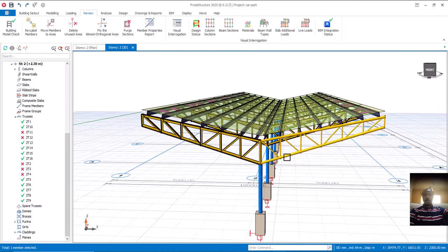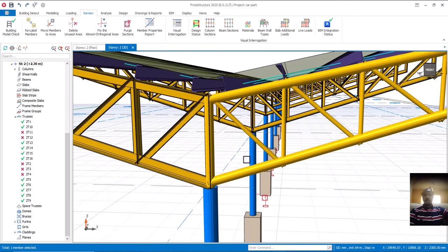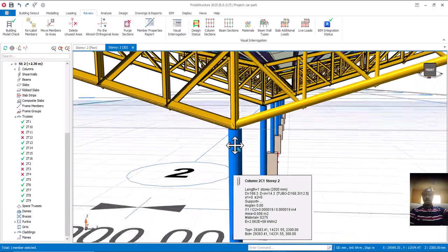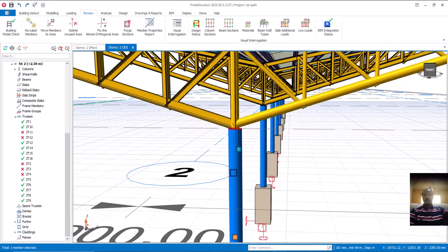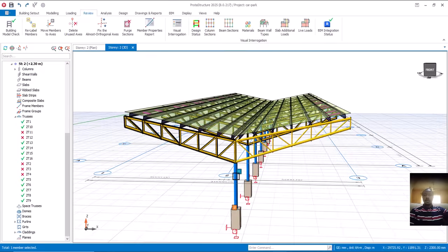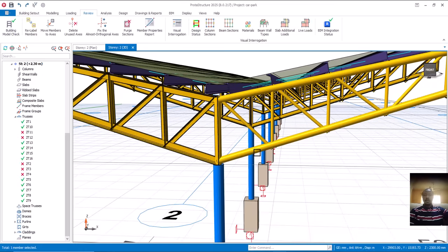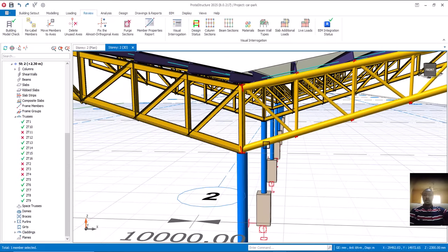If you look at this car park, I purposely used it to explain, because we are using pipes. Speaking generally now, since we are using pipe stanchions, it's advisable that you use pipes for your trusses, because it's easy for welding.